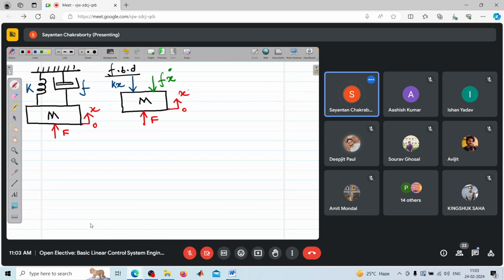Are you sure? Is there anything missing or not? So the inertia part is missing. No, no. Where should inertia come? This mass only, na? That m d2x by dt square is missing. Fine. Yeah. And what about the mg component? mg will be balanced in the static portion when the mass will be released from its initial position. The kx will be balanced with mg because. Right.